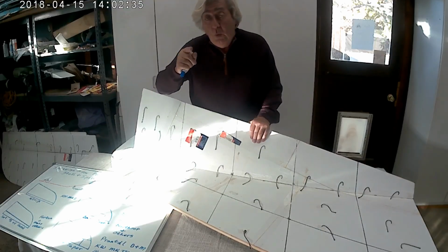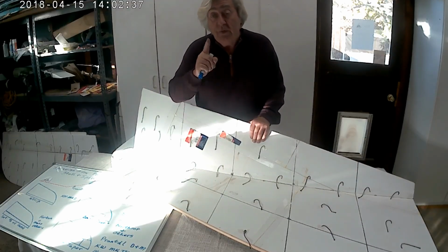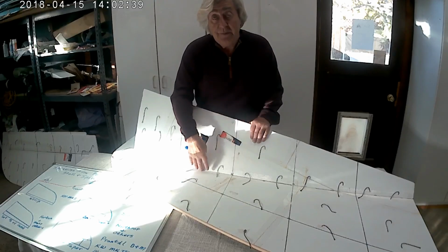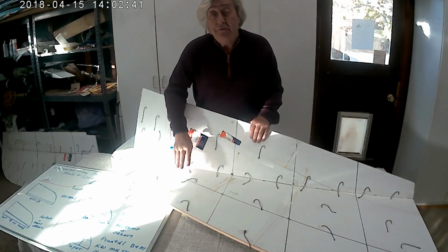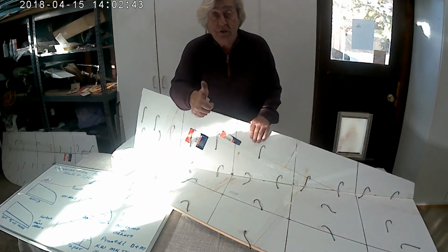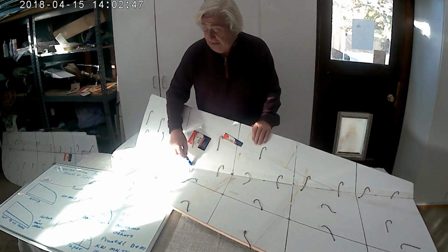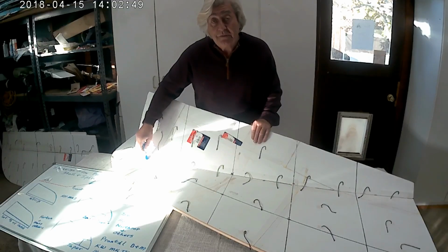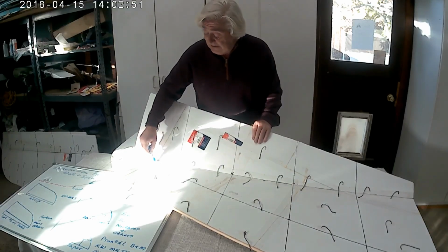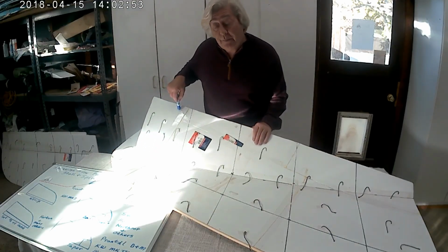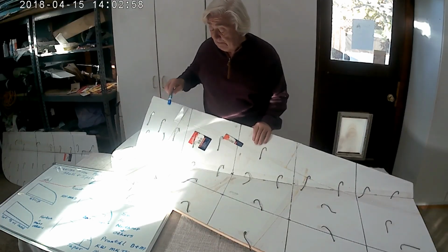So, we know one of them has to do with the change in washout on the wing or the shape of the elevon. Reverse taper gives you better washout at the wingtip, which is a good thing for stopping spanwise flow. We now understand that if we put the hinge line where the momentum of the flow is the highest, it has the highest probability of getting straight up over the control surface without separating or going spanwise.